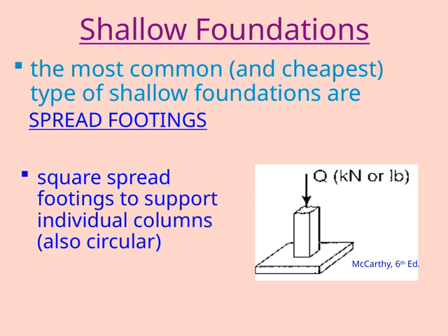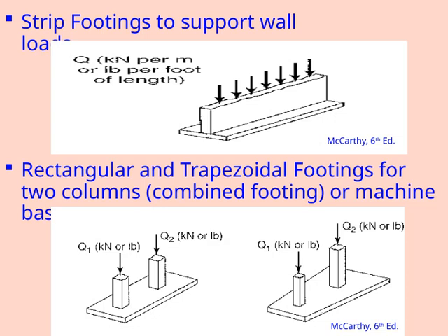Remember, choosing the right foundation depends on the load and the soil conditions, but in many cases, spread footings are the go-to solution. Let's talk about strip footings, which are used to support wall loads. These are essentially continuous strips of concrete that run beneath load-bearing walls to distribute the weight evenly across the soil. They're a simple yet effective solution for supporting load-bearing walls in many types of structures.